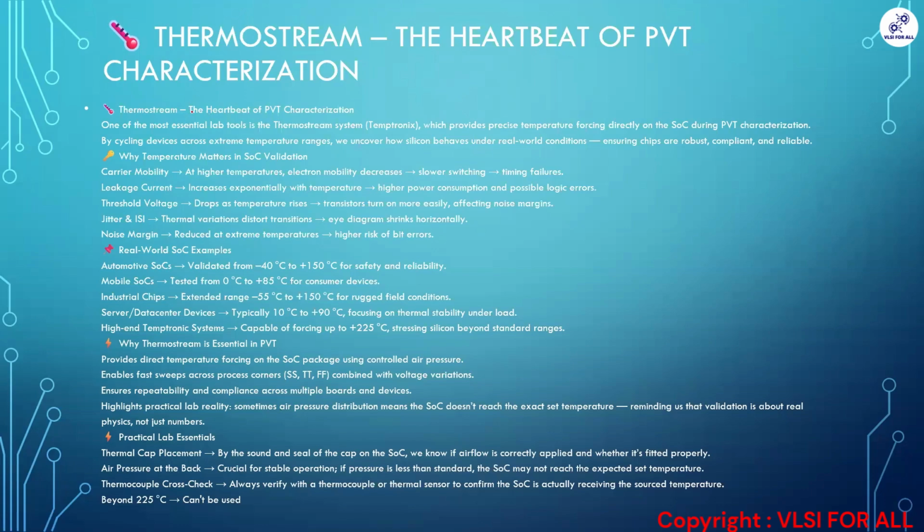So for Thermostream, basically we use Temptronics Thermostream, and it is used for precise temperature sourcing on the SOC during the PVT characterization by cycling devices across the extreme temperatures, from normal, cold and hot. We keep cold first then hot, because in cold temperatures we'll see ice formation.